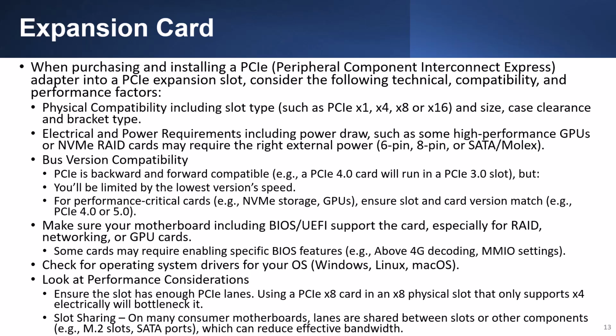For bus version compatibility, PCI Express is backward and forward compatible, such as a PCIe 4.0 card will run in the PCI Express 3.0 slot, but you'll be limited by the lower version speed. For performance-critical cards, ensure slot and card versions match.